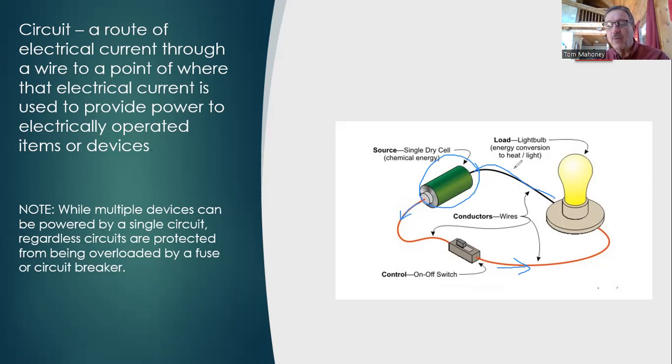This ground can either be a wire or it can be bonded straight to, for example, the aluminum structure of the aircraft at the place where the item being powered is operating, and then it can pick up another ground closer to where the battery is. So the ground can actually be the aircraft itself, as long as it is able to conduct electricity.